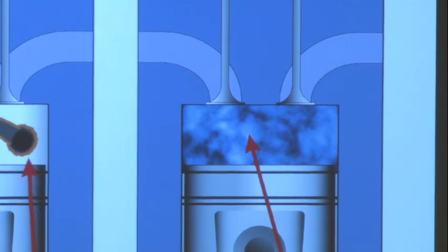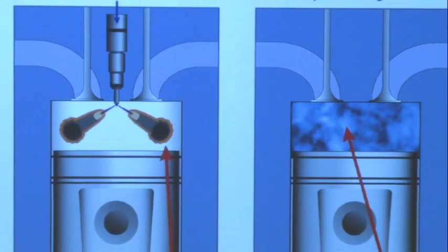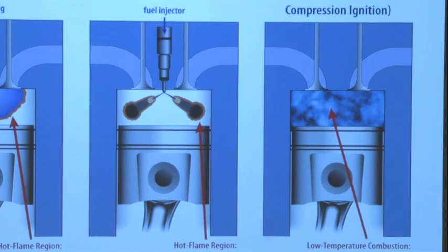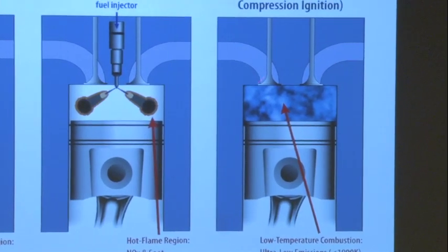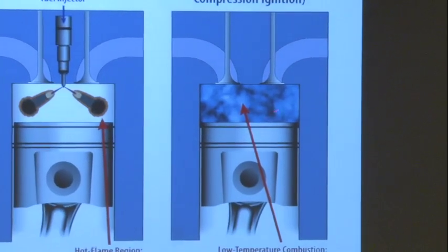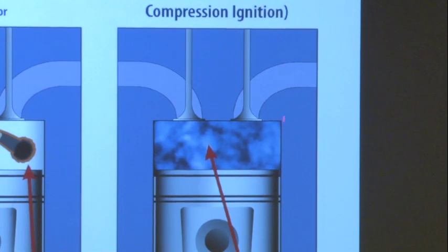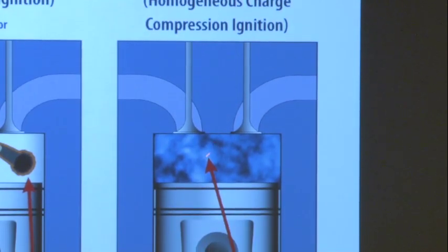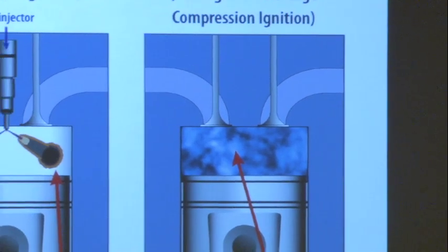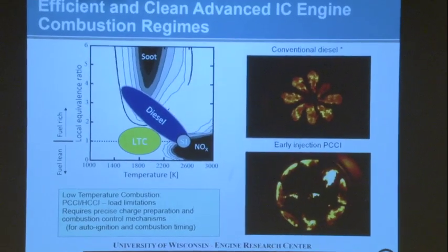So in this last mode, there's been a bunch of variants of this. There's been premixed charge compression ignition, and spark-assisted compression ignition. There's all kinds of variants on this theme. So it's not truly homogeneous, but it is such that you have predominantly auto-ignition with some degree that you can vary of flame propagation. So it's a combination of this so-called mixed mode combustion that's happening in there.